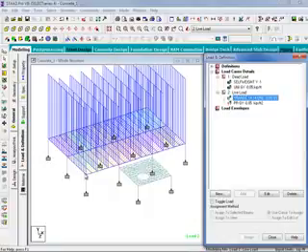Now if I take a look at the model, I can see what the distributed loads ended up being on each member in the model, and the shaded areas basically indicate the different tributary areas that were applied to each beam member. So there's no further step required when doing a floor load. And again, we entered a Y range, and this level just happens to be at 14 feet.